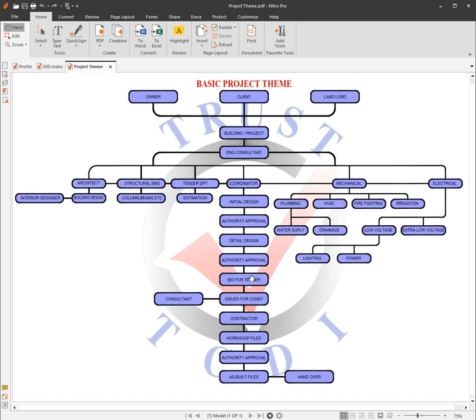So what happens for the tender? As per the design, the estimation and tender departments check BOQs, bills of quantities, for every service, and they make a list. They have a vendor list. They select the materials and the quantity of materials, and after that they make a rough price which is the bid for tender. Then they check for contractors who can go with this price, and once a contractor says, I agree with these prices and I am able to fulfill all the requirements, they issue these drawings for construction to that contractor.